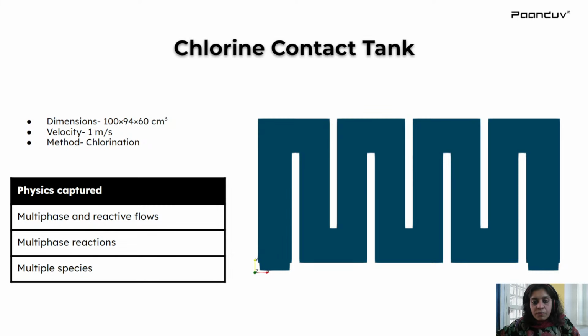Another aspect of this particular problem is multi-phase modeling. You have different species in the system. You have air on the top, and you want to model the multi-phase system, which is more complex than a single phase modeling system. Another complexity can be added by incorporation of the reactions, because this system itself is a complex system. You have tons of moieties, tons of impurities here.